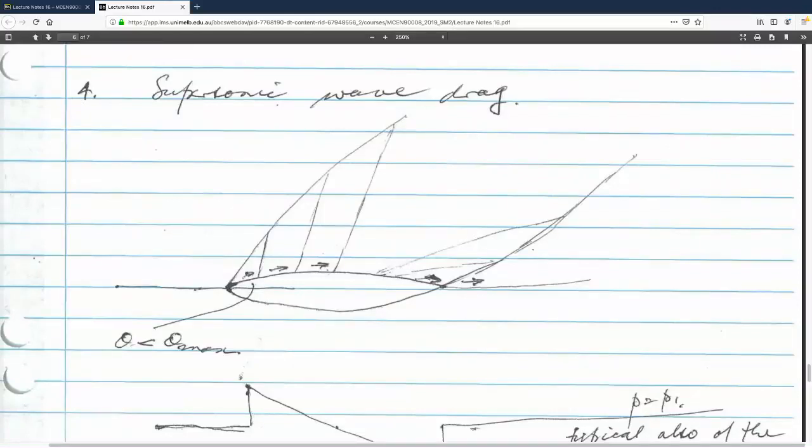And then I'm coming here, and these Mach lines are still expanding, but then I get to this point here, and because I have a flow coming from here, it has to be horizontal. What is the only way I can do that? If this is a high Mach number here and I have to turn it, I have to turn it through a shock wave. So I have a shock wave here, just as I had a shock wave here. Shock wave at the end.